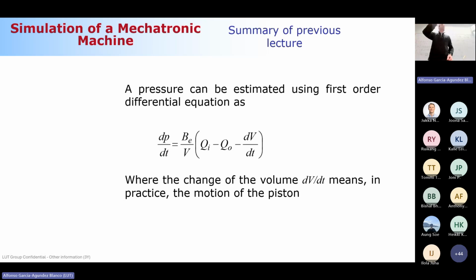So if you have in the hydraulic cylinder force the product of the areas times the pressures, these pressures are computed from this differential equation, okay? Are computed from here. Perfect. So what we need to do is to apply this differential equation to each of the control volumes of the hydraulic circuit.